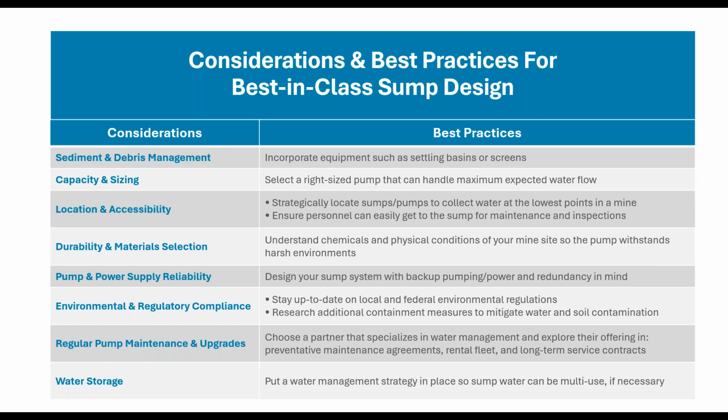So here on the screen, you're going to see some of the considerations for best-in-class sump design, and I'll touch on a few of these here. You can obviously read through, but talking about some of the highlights: sediment and debris. As I mentioned, mine water is going to have small particulate in it that over time will collect at the bottom of the sump, which could clog pumps, restricting their operation and reducing sump volume and efficiency. Proper design should include features to manage and even remove those solids, or at the very least, prevent additional solids from entering into the pumping equipment.